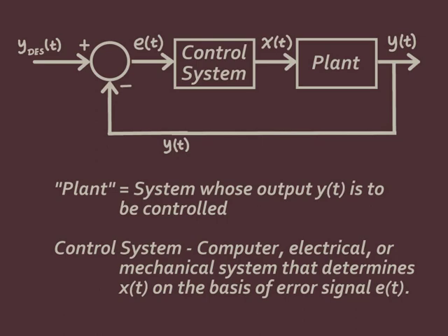The actual chip moisture content would then be compared to the desired moisture content, which might be, say, 15%. This generates the error signal. If this error signal is positive, this means the chips are overcooked, and if it's negative, it means they're undercooked.